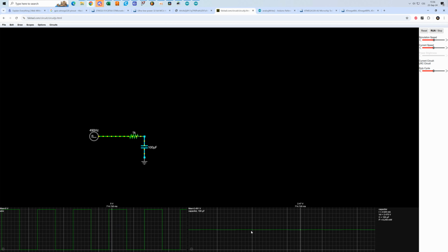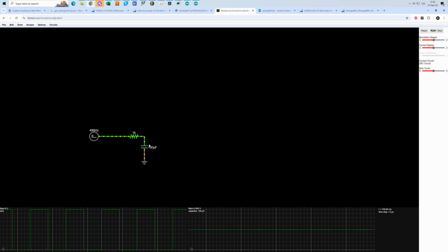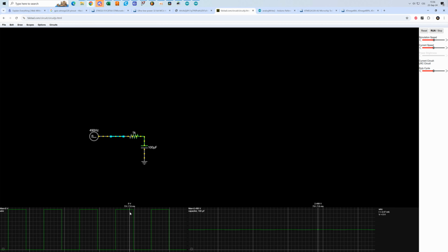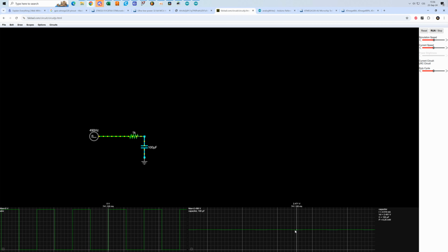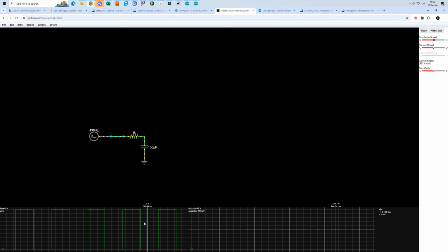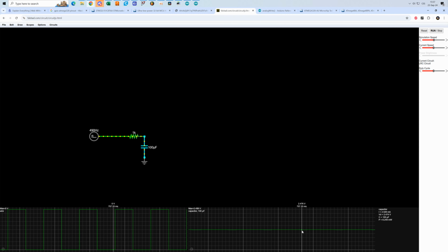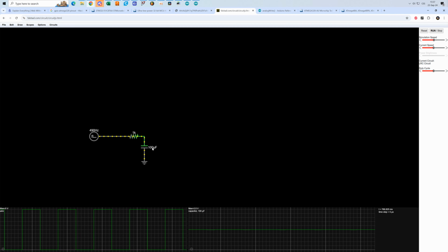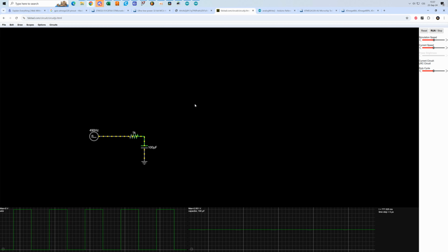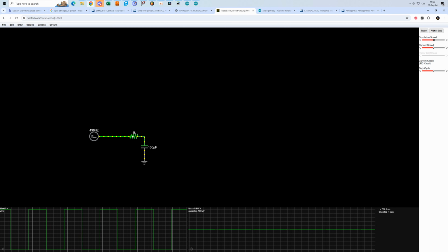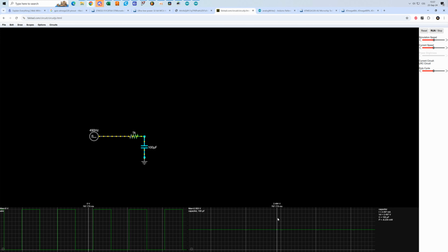So we can see here, this is the average voltage. This is the voltage on the capacitor. And it should not surprise us that with 50% duty cycle, we have 2.5 volts because this is the average. So half the time it's 5 volts, half the time it's 0 volts, meaning the average voltage is 2.5 volts. So this is how you can actually use the analog pin as a real analog output pin if you average the PWM with a capacitor and a resistor like this, right?